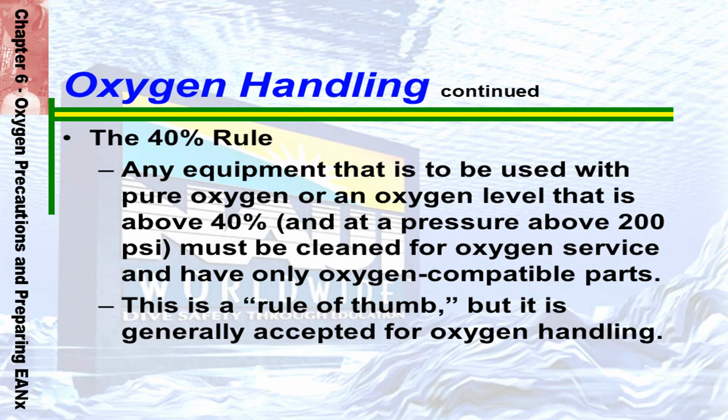40% seems to be a valid limit in the sense that at or below this level, oxygen compatibility problems have not occurred. Above 40%, one is in the gray area for which there is seemingly no firm data. Flash combustion has occurred above 40% oxygen, so it is better to err on the side of safety. Technical divers use higher oxygen fractions, such as in a decompression gas mix, and use scuba equipment that is specially serviced and is fully oxygen clean and oxygen compatible for these special applications.